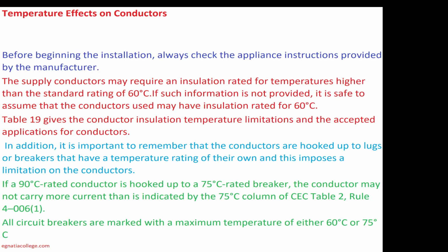Temperature effects on conductors. Before beginning the installation, always check the appliance instructions provided by the manufacturer. The supply conductors may require an insulation rated for temperatures higher than the standard rating of 60 degrees Celsius. If such information is not provided, it is safe to assume that the conductors used may have insulation rated for 60 degrees Celsius. Table 19 gives the conductor insulation temperature limitations and the accepted applications for conductors.